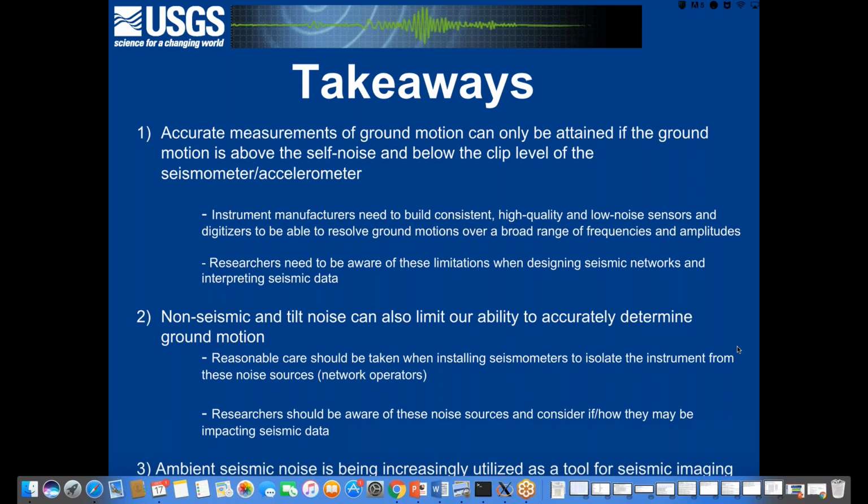How can you mitigate tilt signals on instruments installed on the surface? There's been some work by Emily Wolin and others that if you put the instrument on a more rigid surface, you can mitigate tilt. So if you put it in soft sandy soil, these atmospheric driven tilt signals are likely larger than if you place the instrument on granite where possible. I know that sometimes when we make site selections, we don't have the luxury of always putting our instruments on the most stable